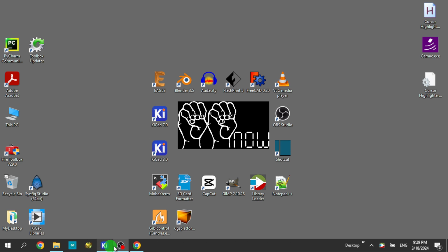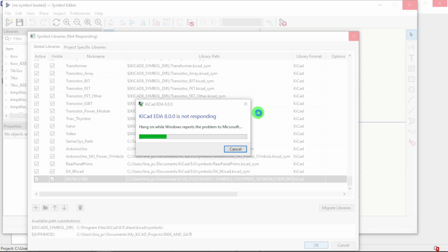So now here, I'm going to move this one here. I'll go to file, symbol properties. I don't want to call it IC, I want to call it U. So now it's going to be with U, and its number of units is only one. So now if I want to move this, I can select move in the center, and maybe move this to the bottom, move this over here, and so forth. So save.